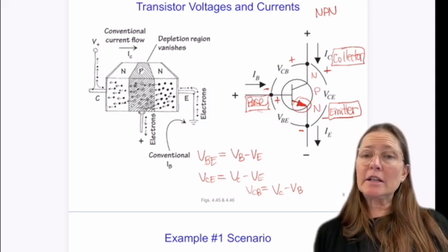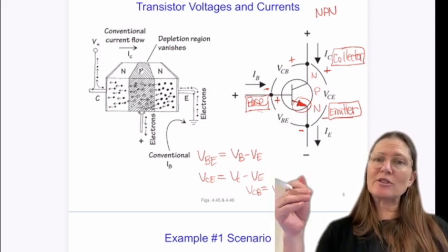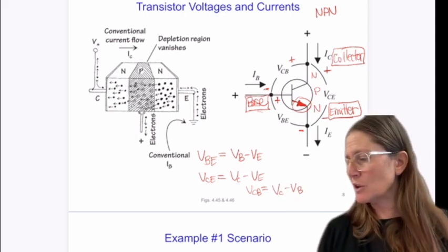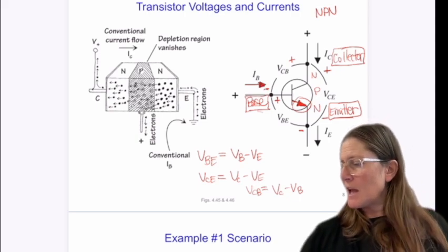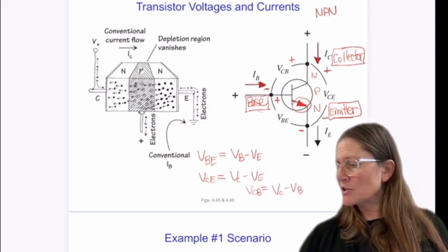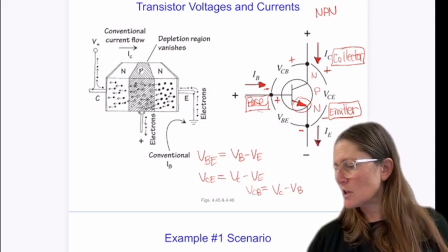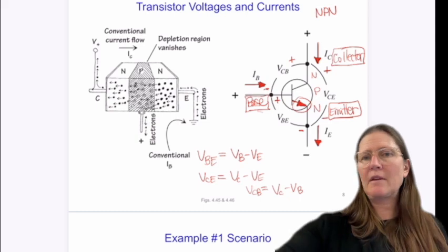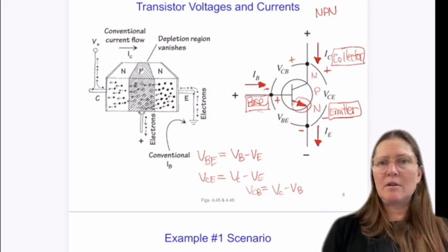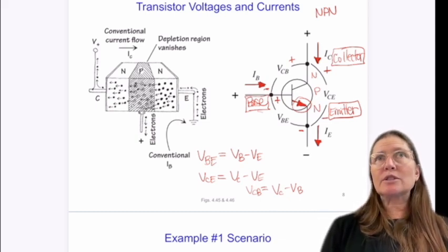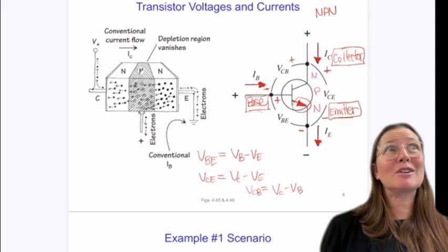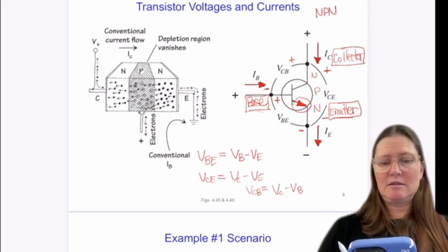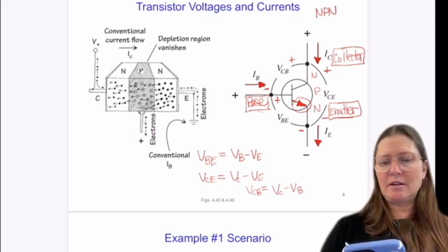All right, current in here, as you saw, the electrons were actually moving out of the base, which means the current flows into the base. And then it flows from the collector side down to the emitter side. All right, questions about the symbol, locations on it? Okay.